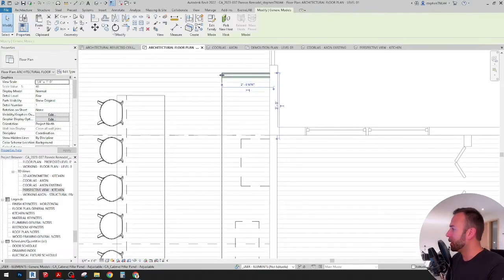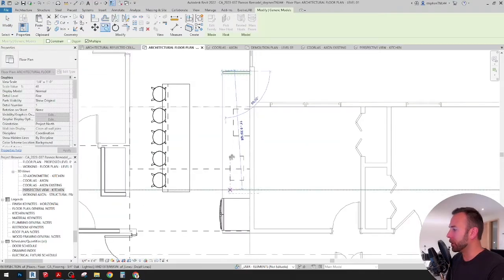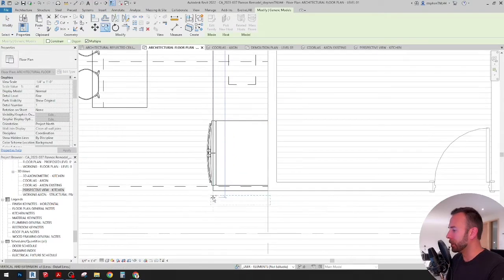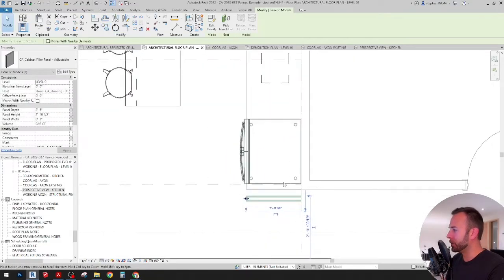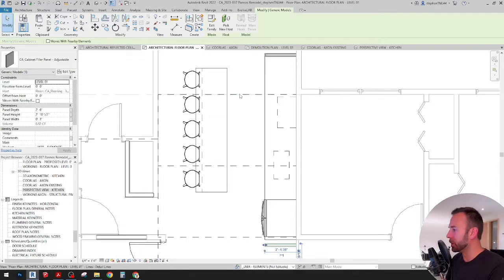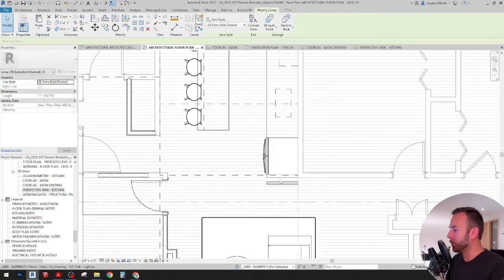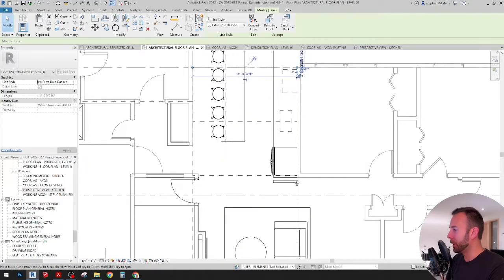So we've got that end panel in on that side. I'm gonna bring another one over to this side, and you may have seen in the perspective view before, we do have some beams running across the space. There's one existing here that cuts across, and then we removed a wall here that was load bearing, and so we're going to put another beam up in the ceiling here to support the ceiling.